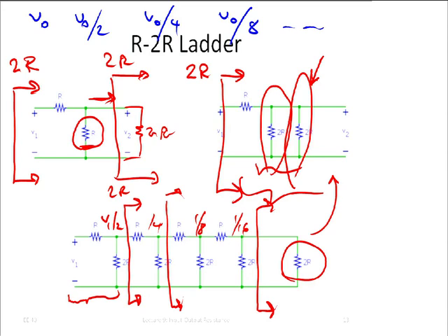every stage. Now, in practice, of course, when you actually make this, the values of the resistors R are not going to be all identical, right? They're going to vary a little. One is a little bit too big, the other one is a little bit too small, and yes, then you start getting errors here. So it depends on what you want to do. For 8 bits, you need about 1% accurate resistors. There are lots of much more clever tricks that you can use. That's another thing that we're not going to talk about in 40, but that's a very common problem in electronics.